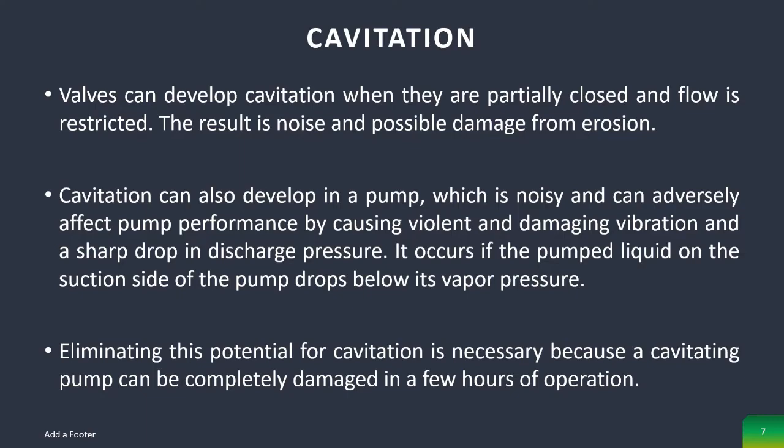Cavitation can also develop in a pump, which is noisy, and can adversely affect pump performance by causing violent and damaging vibrations, and a sharp drop in discharge pressure. It occurs if the pump liquid on the suction side of the pump drops below its vapor pressure. Eliminating this potential for cavitation is necessary because a cavitating pump can be completely damaged in a few hours of operation. So, delikado talaga yung cavitation.